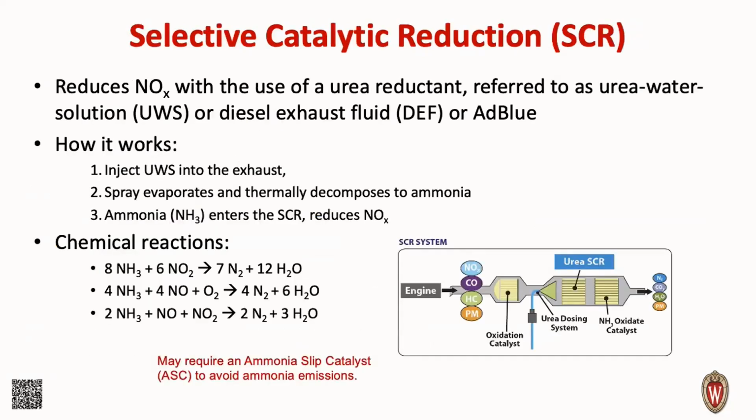Next up is the Selective Catalytic Reduction Catalyst. This one reduces the NOx from the exhaust with the use of an additional reductant, which is a urea water solution. Urea is a salt, and we mix it in with water to create the urea water solution.